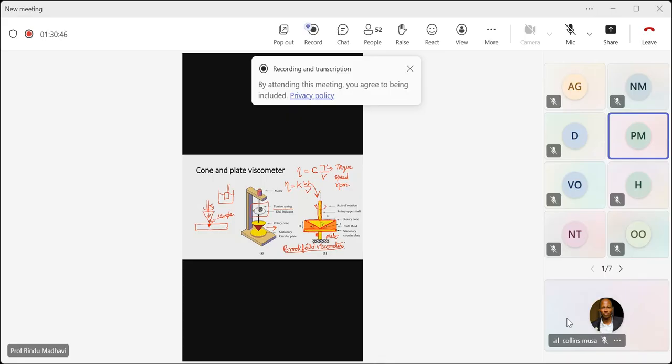But the equipment directly gives you the viscosity at the recorded temperature. Equipment knows the temperature where it is measuring the viscosity. It will give you the viscosity at a definite measured temperature, so that you don't have any errors. When it is measuring the temperature, it will give you the respective viscosity. The same thing is applicable for the cup and bob viscometer also.